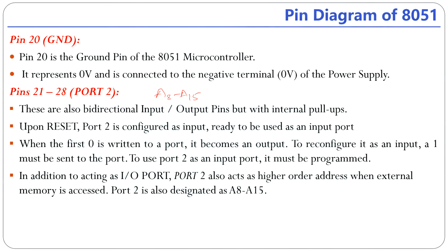But you know that already, I mentioned it for port 1 and port 3. Similarly, here also you can program it as input or output by writing logic 0 or logic 1. Logic 0 for output, logic 1 for input.